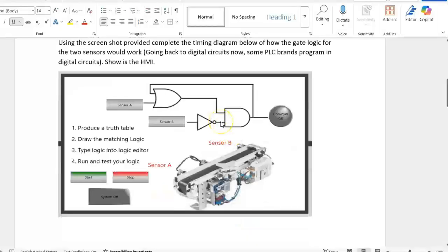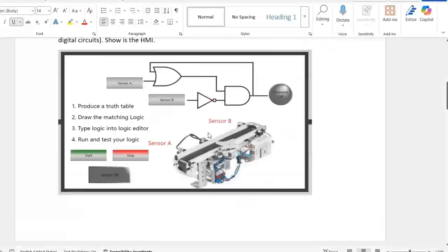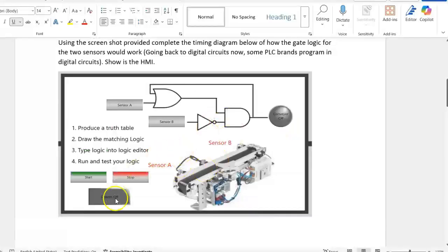It is Boolean. Some of the early PLCs, you had to program them in Boolean, and you would actually type in sensor A or this output into an AND, which would be sensor not sensor B, and not this input, or and this input would then control the logic. So that lets you know how to sort of get started on this logic.